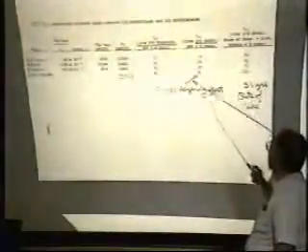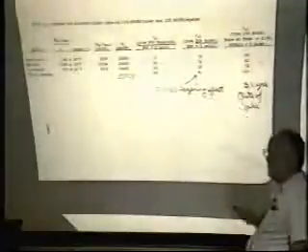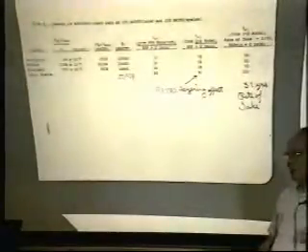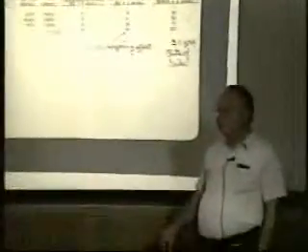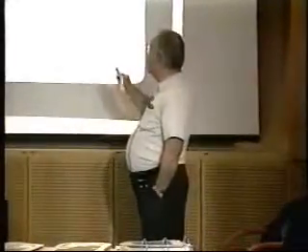And again, this 91 years, this long producing time is basically a layering effect. So if you go back and you see some oil fields that have been producing since 1919 and they're still on production, you know what's the cause of it. It's layered, no crossflow. The same thing with gas fields that have been producing a long time. This is a fundamental characteristic of a layered no crossflow reservoir. It's going to have a long life, and there's nothing you can do about it. Again, you do infill drilling, you accelerate.